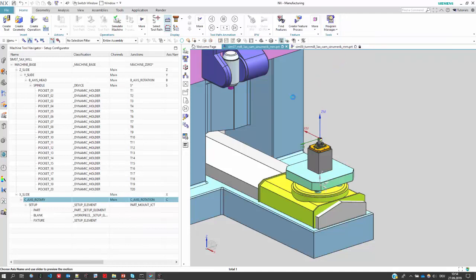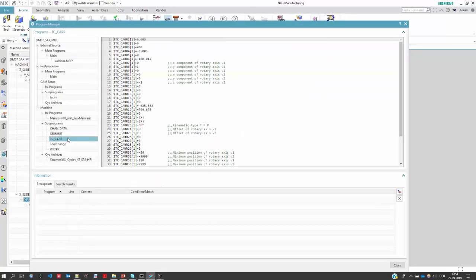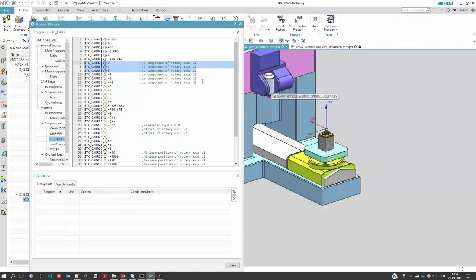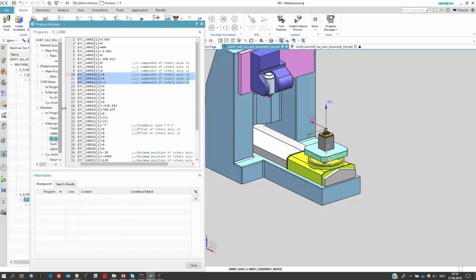So you also can see this here in our machine settings in the tool carrier data set. So we have in here our vectors from the rotary axis. You see here our first axis is the B. That's our tool axis here. It is here 0, 1, 0. It's positive. And here our table axis, which rotates the part, is a -1 on your Z-axis, because you have to look at the part rotation. And this is how you easily can check this.